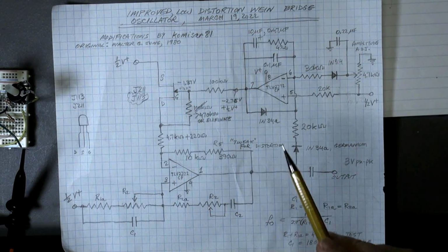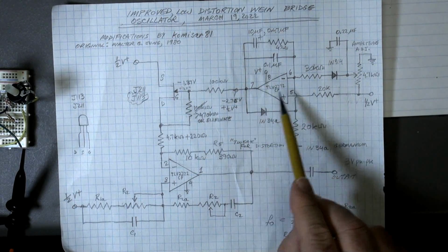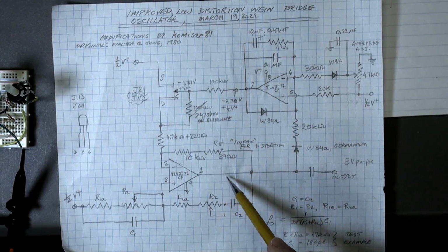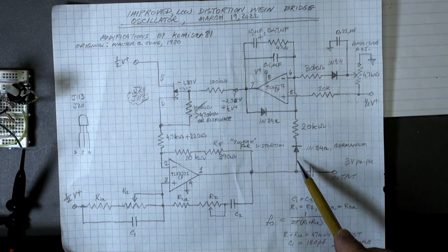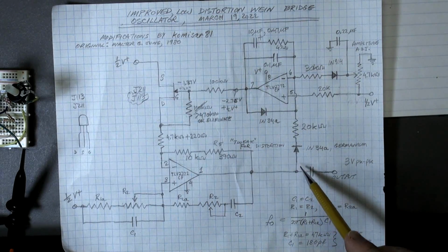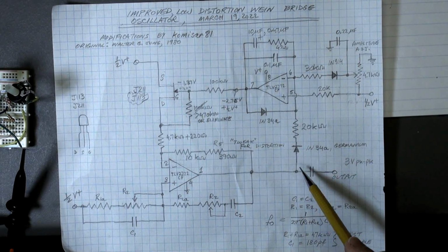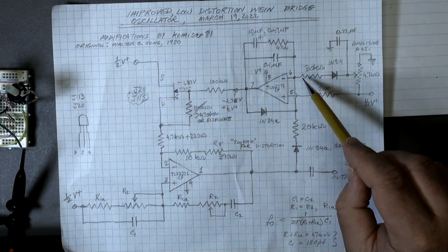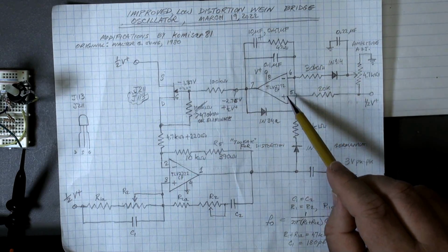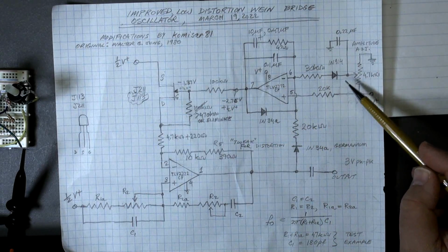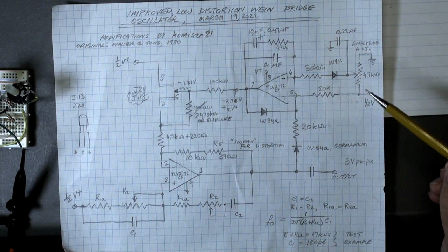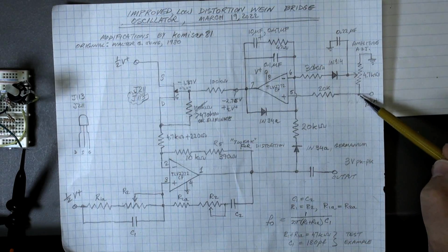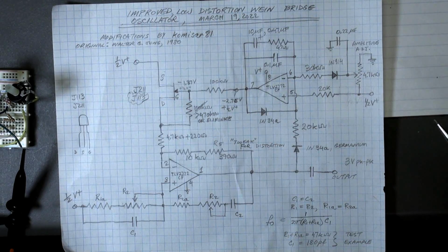And the control voltage comes from this integrator comparator, which is taking part of the output signal, positive going voltage swings, going through this low voltage turn on germanium diode, and going into a summing point at pin 6, and it's being summed with a reference voltage, which is adjustable in between ground and this 1/2 V plus, which I call virtual ground.